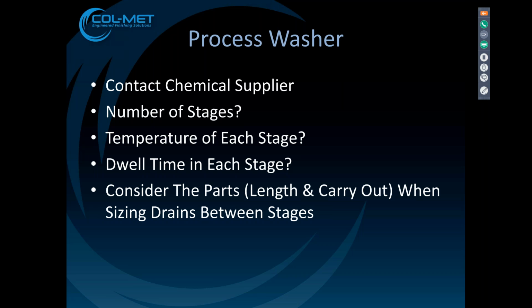However, when a part has carry out, because of the design configuration, the geometry of the part, we need to know that, because we need to be able to make the drains longer so we don't contaminate one stage to the next. It's very important that we get this information.